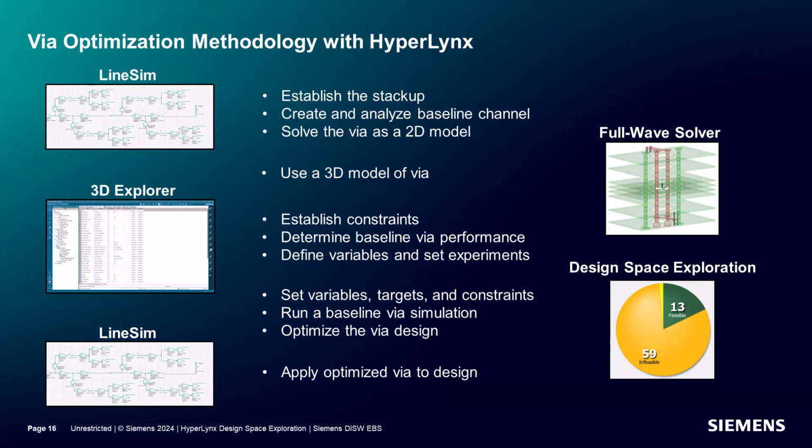That's where Full Wave Solver comes in, to review the 3D model of the VIA. Then 3D Explorer to set up the baseline for a 3D VIA, understanding the reference point figure of merit that you'd like to see improvement from. In this case, impedance range. Here we would also set up any sweeping parameters.